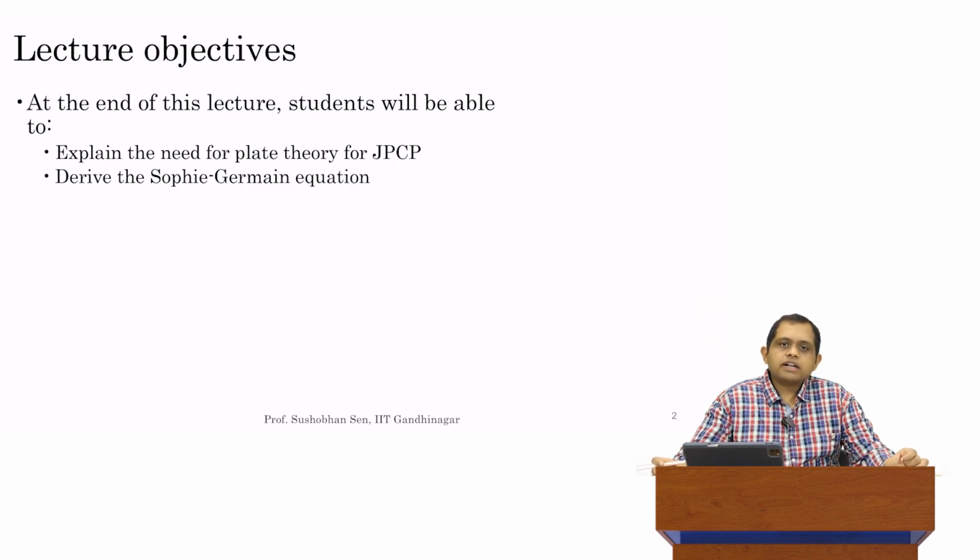So in particular, we saw that for a rigid pavement, the slab is modeled using two properties, which are the elastic properties, namely the elastic modulus and the Poisson's ratio. That's one. And then we saw that the subgrade is characterized using what is called the modulus of subgrade reaction. In short, it's sometimes also just called the K value. So what we saw was that we had various ways of measuring these properties directly, but in general, those techniques are not particularly convenient. So we saw there are simpler techniques and a variety of correlations that we use to relate these properties. Finally, we looked at certain distresses which develop in rigid pavements as well. So that was module one.